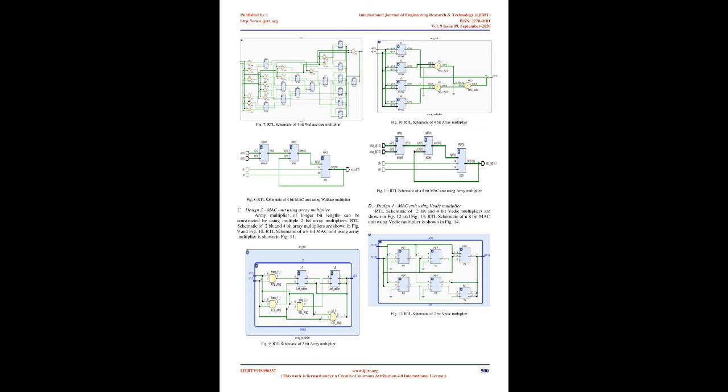If inputs to the multiplier are of bit size n, then the adder should be of bit size 2n, producing an output of size 2n plus 1. Carry save adder, carry select adder, ripple carry adder (RCA), and carry look ahead adder (CLA) are among the widely used adders in the design of digital logic processing devices. Propagation delay and critical delay are 2 important parameters to be considered while using adders. In this paper, carry save adder is used in the design of the MAC unit.